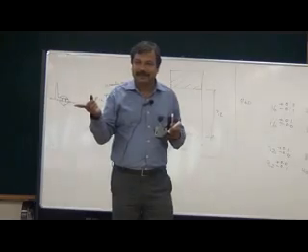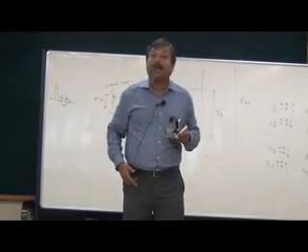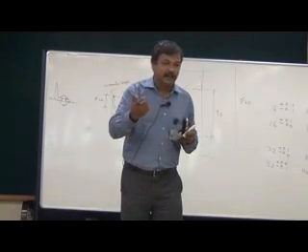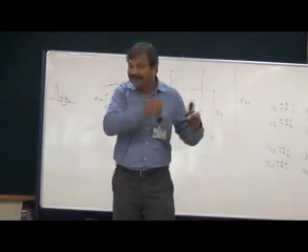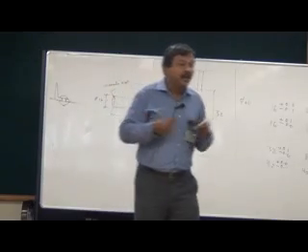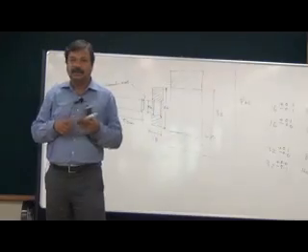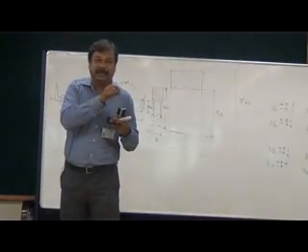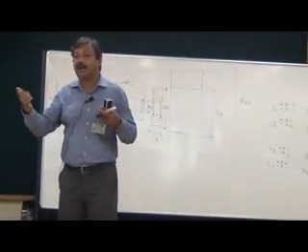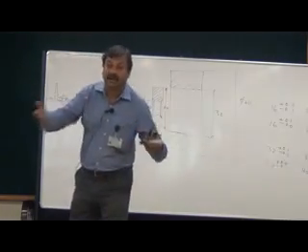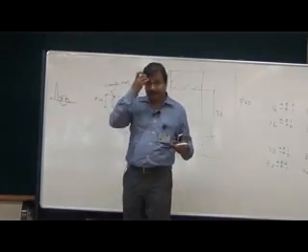You have achieved both. You are able to easily put the rivet, and you are achieving something more. When the rivet material is brought to room temperature, it will undergo a process called age hardening. We will study about it later. The aluminium alloy undergoes age hardening or precipitation hardening, and after some time it will become very hard, very strong.